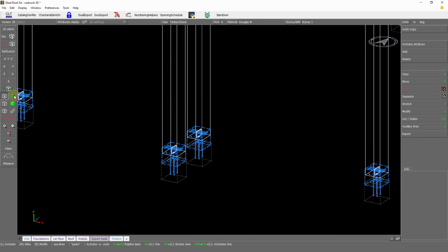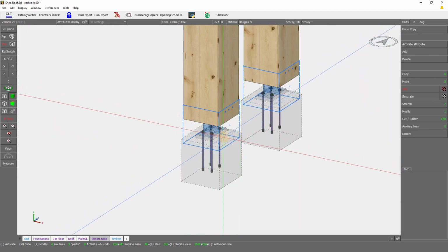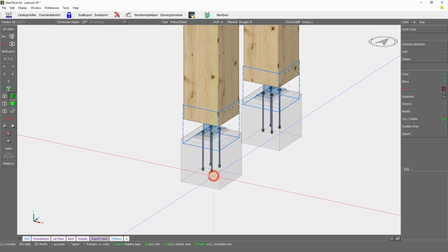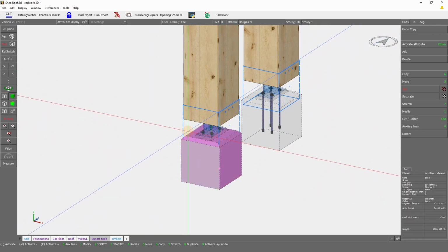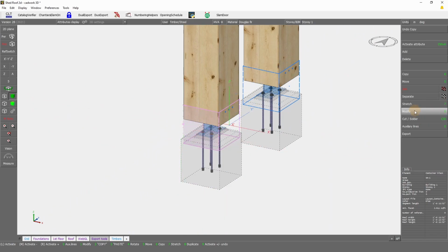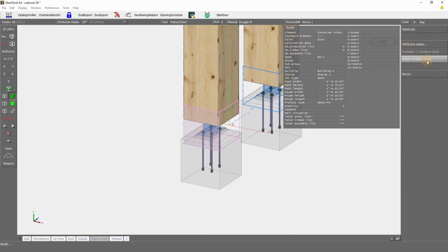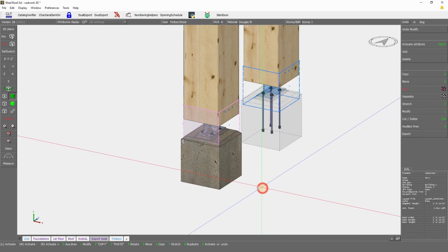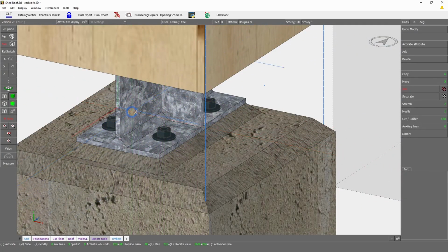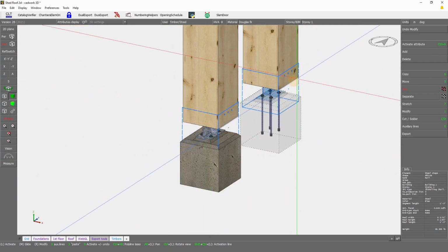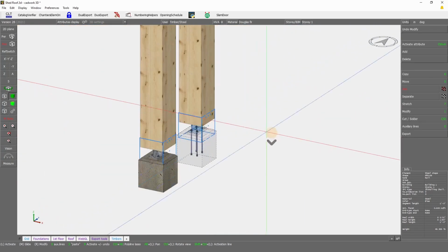so if I want to change something, this is really important. If I want to modify this, what I need to do is release the content, so just remove the container block. So if I go Modify, Option, and Unlock Container Blocks, now of course I can select this and modify, do anything, but it's now unlinked from the other ones.